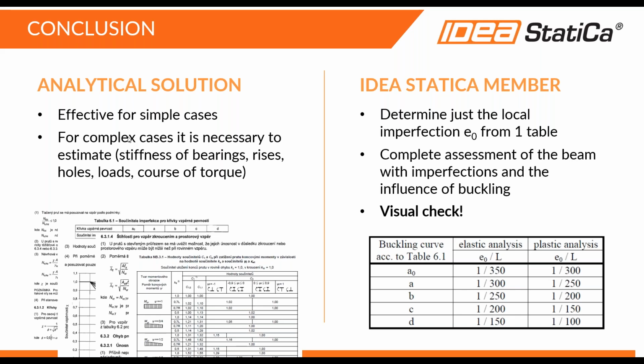And what's the most important for me personally is the visual check, right? So we saw in IDEA StatiCa Member how those buckling shapes look like, what's going on in the member, how stresses look like, right? We could immediately react on what's going on, put some additional support, strengthen the beam, or add some stiffness and so on.